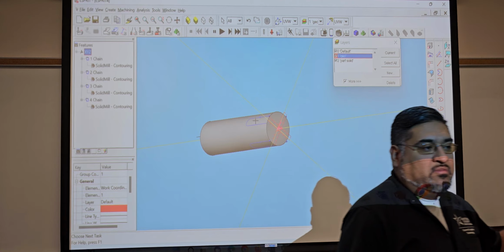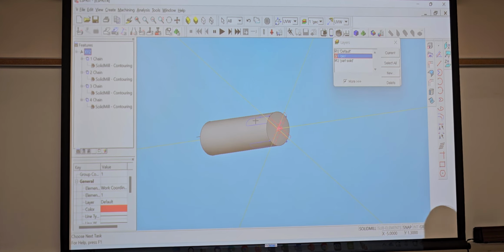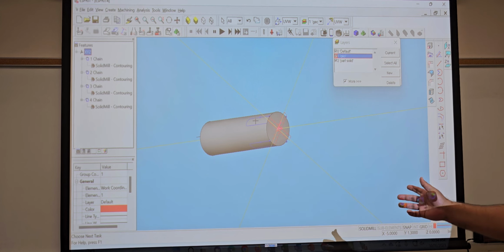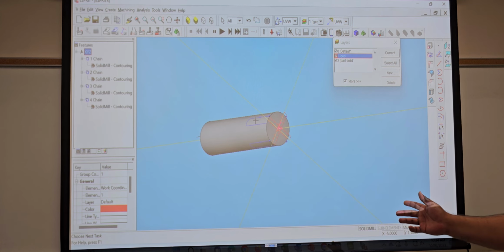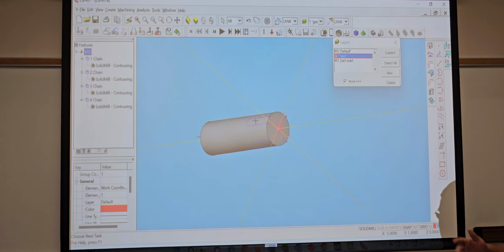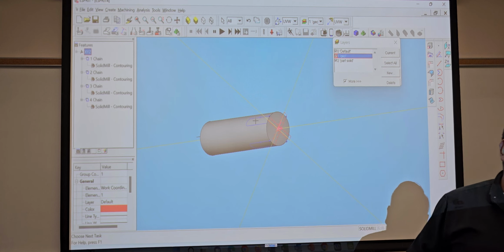It happened while you guys were practicing, because we had the bigger one, the smaller one, and then the one all the way down, right? So some of you guys didn't chamfer the one all the way down. If I do it like this, how do I know whether it's gonna chamfer or not? I don't. Does that make sense? But if I did that on the drawing, and then I'm looking at my toolpath, and I see that it didn't do it, then I could double check like a safety net also. Hey, it didn't do that. You get what we're saying? So that's how it helps you if you do it or not, right?